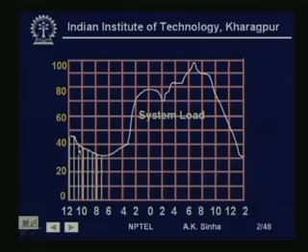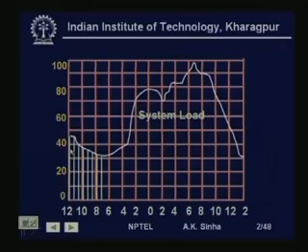In fact, what normally we do is we take small time slices in which we consider the load to be constant. We can keep the time slices every minute or a couple of minutes, in which period we expect very little variation in load, and therefore, we consider it to be constant for that period.